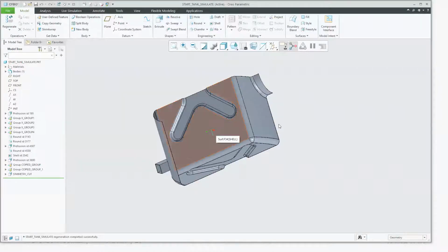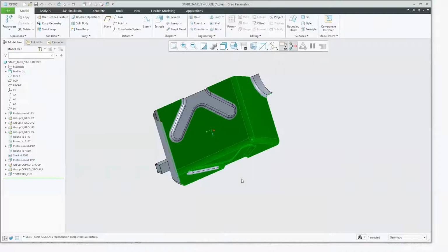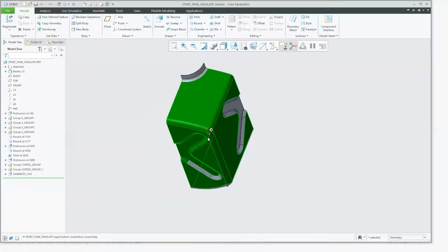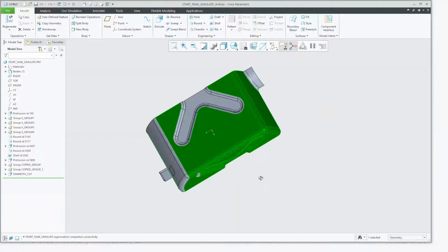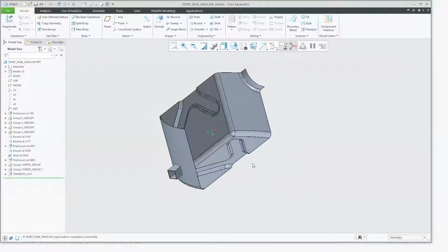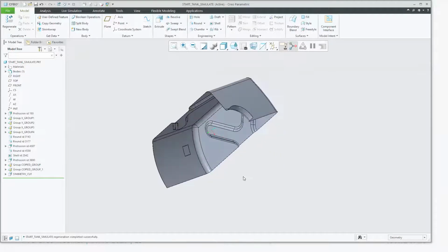There are quite a few ways, but it might take forever to do this, or maybe I know I can do my rectangle select and I can do it, but it picks surface on the other side, right? I can do left drag, right drag, depending on if it's fully enclosing. All those options are available. It still takes some time. This is where that seed and boundary becomes very useful, right?